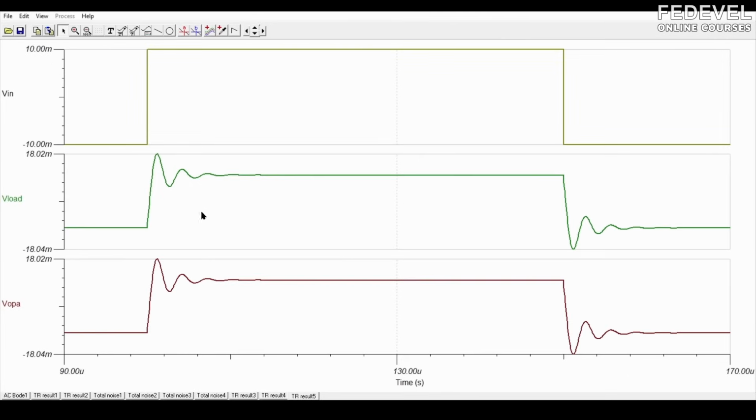So you'll see it doesn't look really horrible, but instead of having this nice square wave on the output, we have overshoot and ringing, and depending on how large that capacitor is, this could actually just become an oscillator. So the different capacitors will cause different amounts of overshoot and ringing, and it might look like it kind of settles out here. But if you were to zoom in on this, you might see very tiny oscillations that are unacceptable for good accuracy.